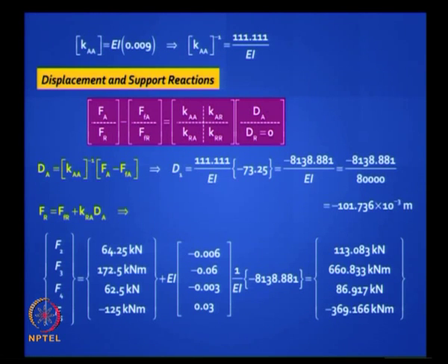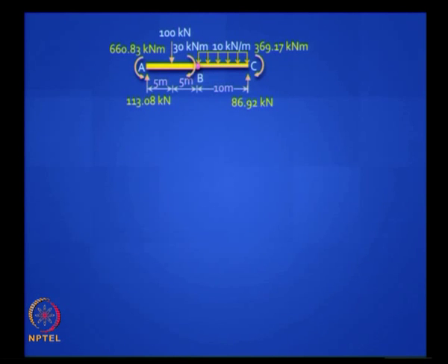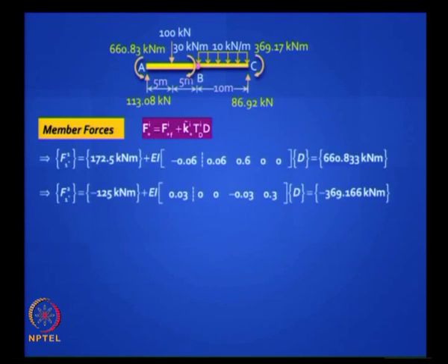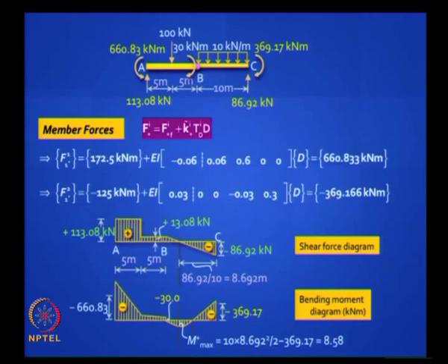Find out the support reactions, they match with what you solved earlier using the clamp, but this is much easier. One unknown here, and there you had to bring in the clamp. So next, member forces, same procedure, same member end forces, same shear force diagram, same bending moment.